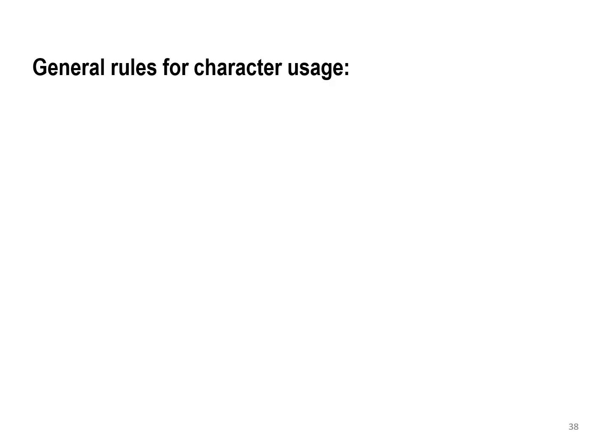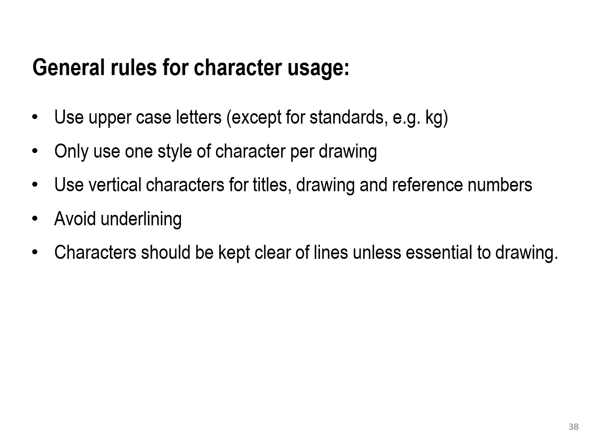Some of the general rules for character usage. First, use uppercase letters in most cases, except for standard units. For example, for kilogram, you should use lowercase. Only use one style of characters per drawing. Use a vertical character for titles, drawings, and references, and avoid underlining. Characters should be kept clear of the lines unless they are essential to the drawing.